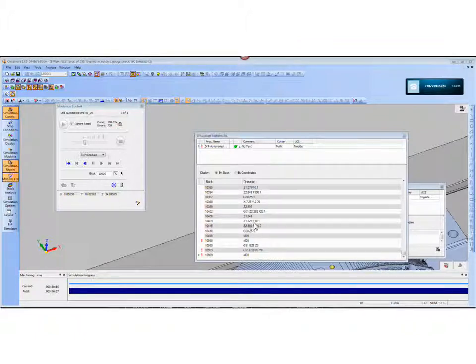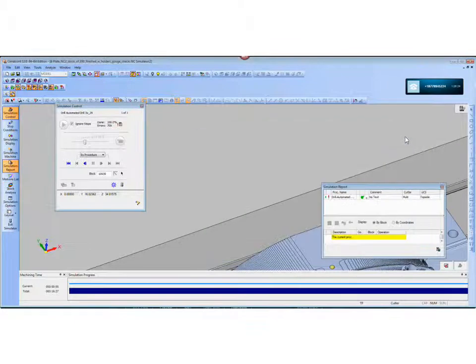And on the retract, you can see that the feed rate is 500% because I want to exit the hole at 500% of my feed rate. I don't see the spindle changing here, but that's just a matter of the post having it pass to the post processor. But trust me, it works. Okay, that's about all I really have to show on the software. Let me go back to the slide presentation here.